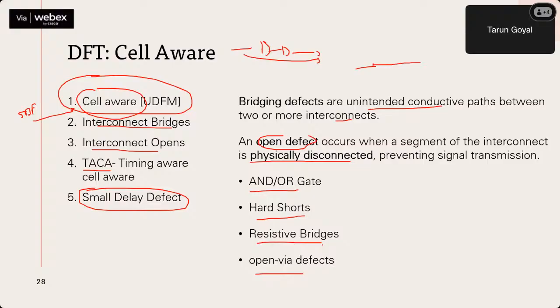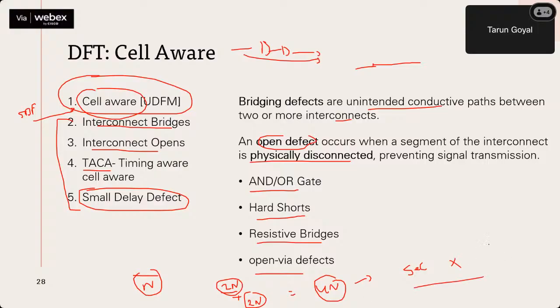So at the end, if for this tech node we were having a number of patterns n, the patterns become 2n via the number of transistors which increase. Along with that, new patterns also via the new faults which we are covering, right? So at the end it was the n pattern which went to the 4n. So now the number of vectors is increased. What does it increase? It increases the test time, which is multiplied by the static cost. So then it's a test cost.